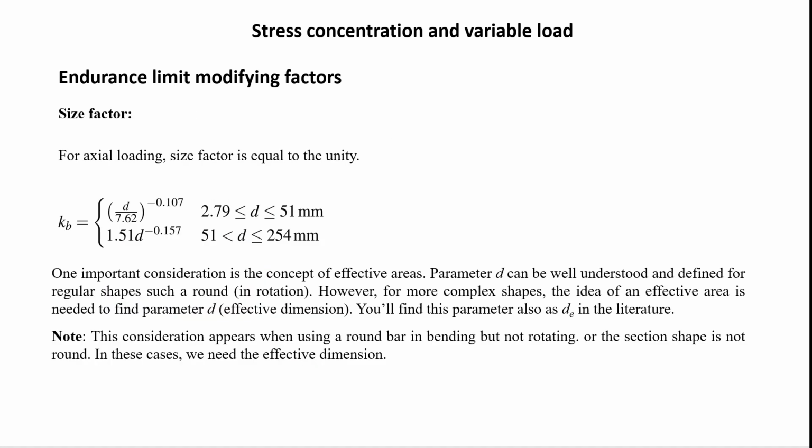Size factor. And size factor is also important because it depends on something very silly but true. The larger the element, the structure, the machine element you're designing, the more probability you're going to have imperfections in it. The smaller one, the less probability you're going to have imperfections. So it's silly, but size factor depends on that.